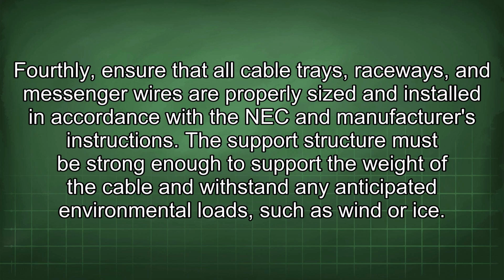Fourthly, ensure that all cable trays, raceways, and messenger wires are properly sized and installed in accordance with the NEC and manufacturer's instructions. The support structure must be strong enough to support the weight of the cable and withstand any anticipated environmental loads, such as wind or ice.